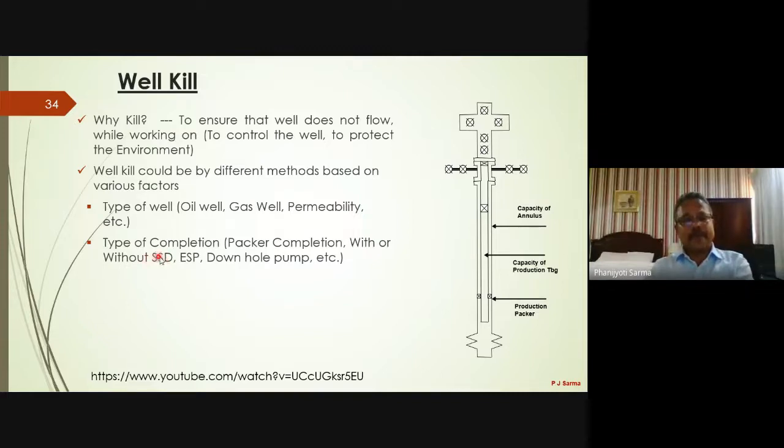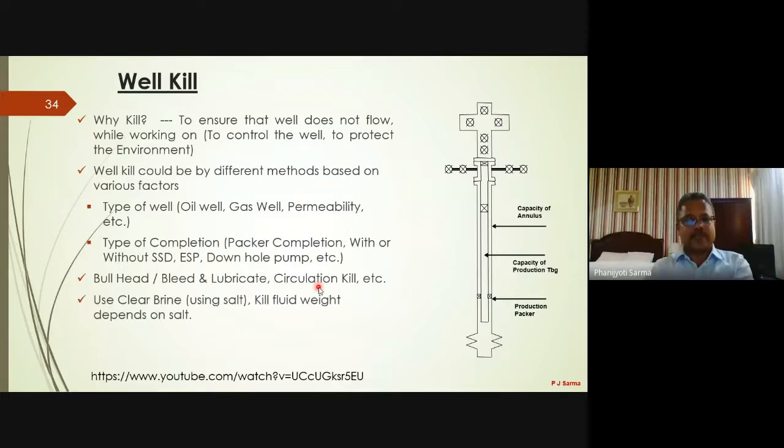By opening this, we can establish communication between tubing and casing, and then circulate the kill fluid from one side and completely displace to the annulus and get the return. So the method could be bullheading if it is a very high permeability, or it could be the bleed and loop method, or it could be circulation kill.